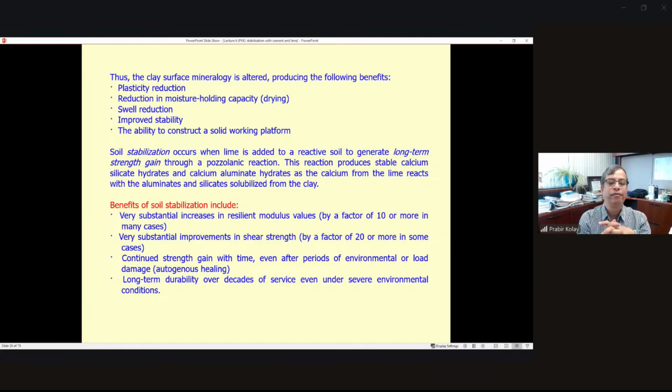Sometimes, when the soil is very soft, there are 2 methods, the dry mixing method: a shallow mixing method and a deep mixing method. Sometimes when the soil is really soft, use cement or lime and mix it together. With shallow mixing, the strength is increased a little bit, cure for 3 to 7 days. And then when it is strong enough to hold the equipment, such as the boring machine, then you go there and make a column for the deep mixing, making a strong column, either cement or lime.